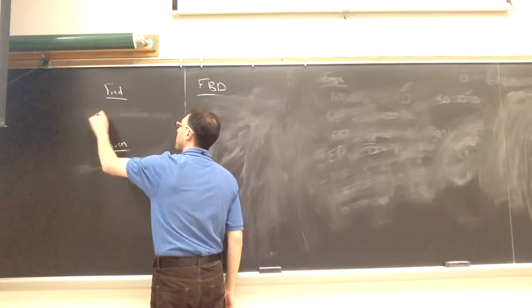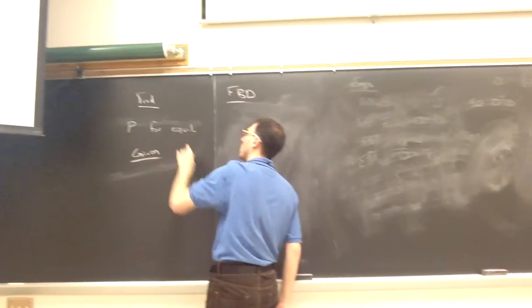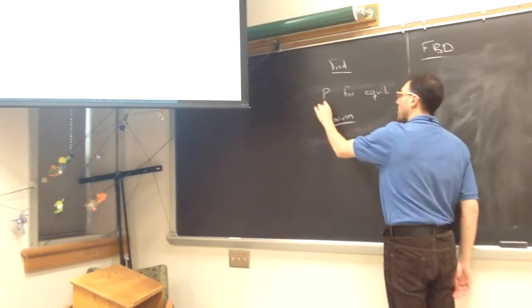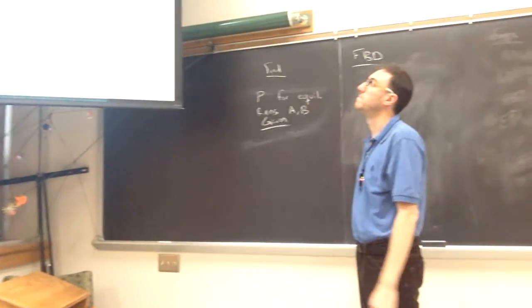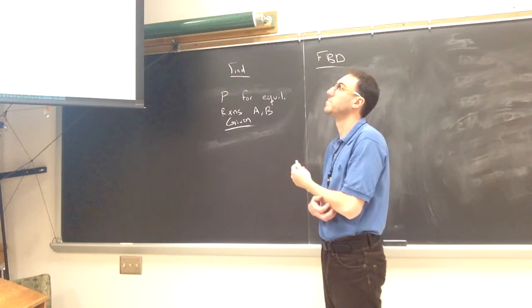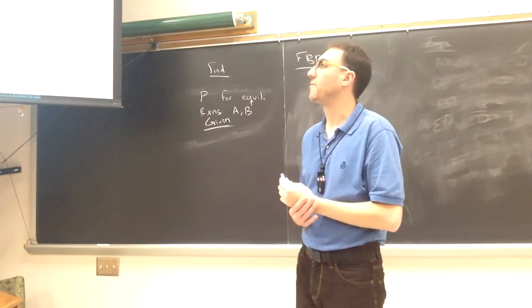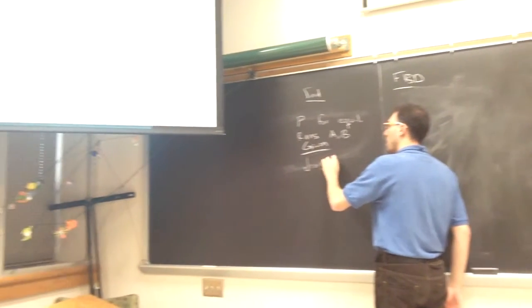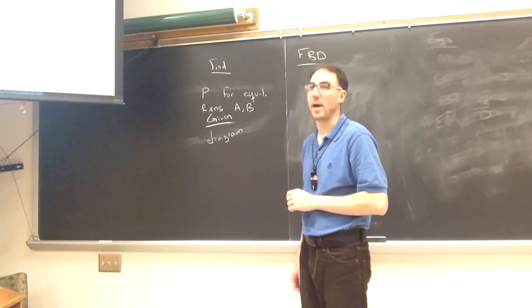So, to find the value of P for equilibrium, we also want to find the reactions at the bearing A and the bearing B. The information we're given is really all reflected in the diagram and then in our free body diagram. They do give us information about the two bearings, and that will be reflected in our free body diagram.